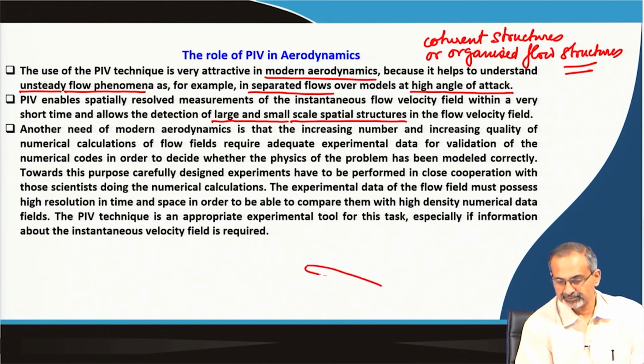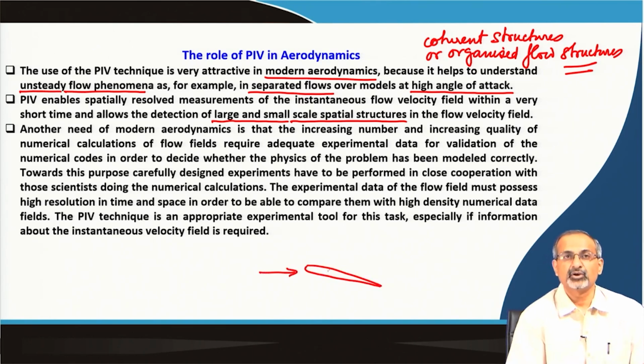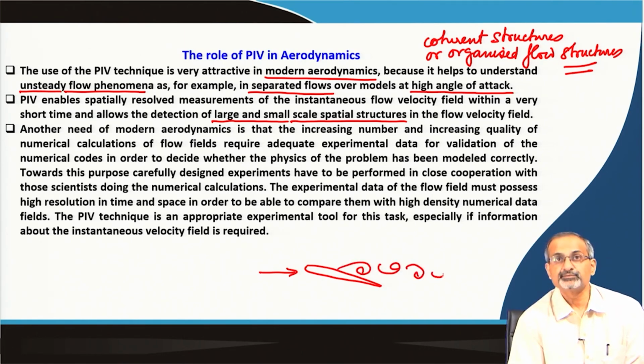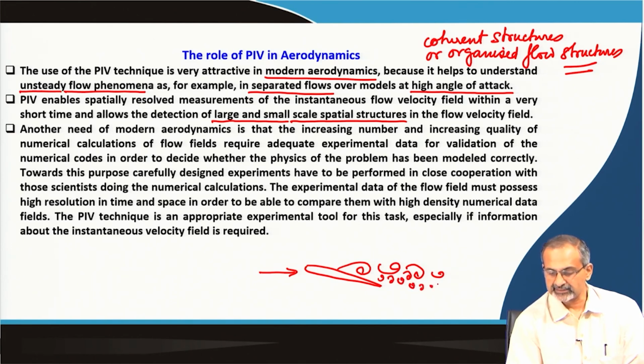For example, if you are looking at flow past an airfoil at moderate to large angles of attack, where the flow separation has initiated, then you see that large eddies are formed around the body and they convect into the wake. Additionally, these large eddies break down into moderately sized eddies and still smaller eddies to extremely small structures. That means there are a range of scales,